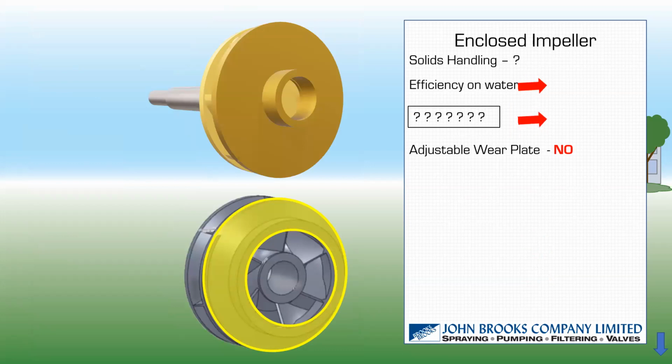Is that required value a calculated value? No. An NPSH required can only be given to you by the pump manufacturer, because they've done the test. Essentially, they do a test that brings out what those losses are as we pump more and more fluid through the pump. And we'll look at that NPSH-R curve in a second.